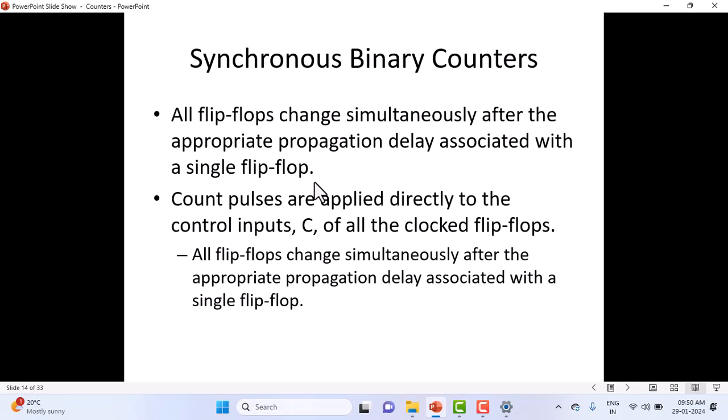That's a propagation delay of asynchronous counter. We should overcome that propagation delay in the synchronous counter. How do you define propagation delay? Yes. How much time a gate or circuit can take to produce the output when the inputs are applied? Understand? But how do you define this for the sequential circuit? The definition holds good for combination circuit. Because there is a combination, let us say for example AND gate, you give input, output will be ready, that's the propagation delay. You can't experience the delay, but there is some delay associated with each and every gate. I am asking, how do you define propagation delay for the sequential circuit?